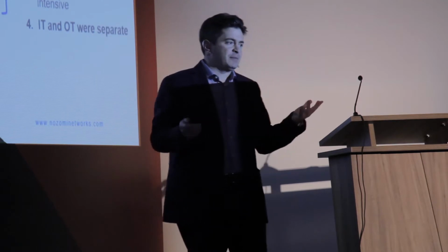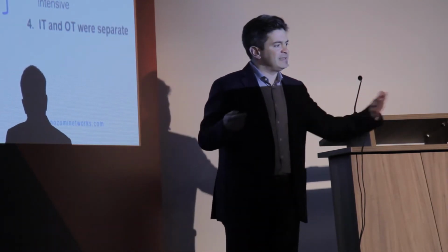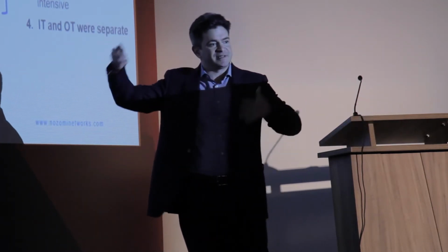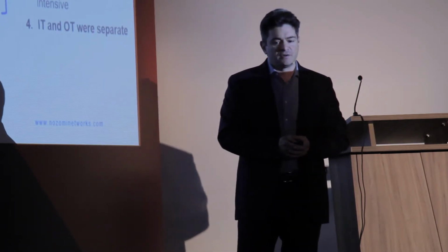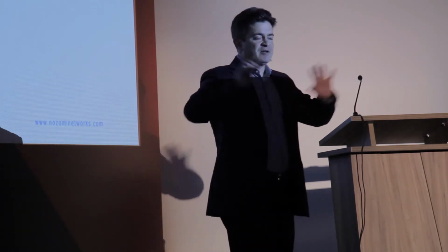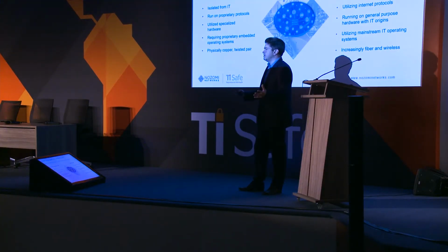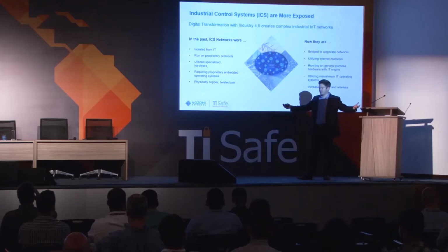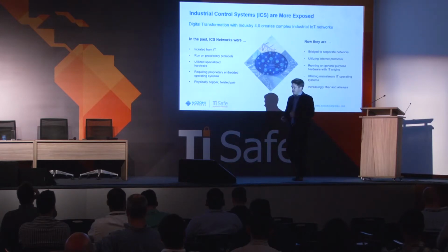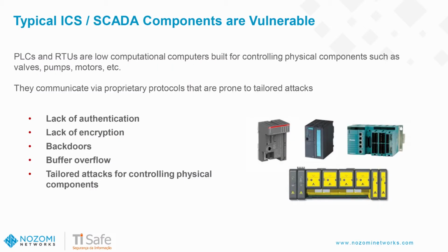And then cybersecurity is an extra step that wasn't needed in the third industrial revolution, but it's a requirement in the fourth industrial revolution. So networks go from being separated, segmented, having proprietary hardware, proprietary protocols, proprietary software, into a world where everybody's using Windows systems, all the protocols right on top of TCP/IP. TCP/IP wants to connect to the rest of the world, and the endpoints of our networks are not really prepared. Our networks' endpoints don't have any authentication.